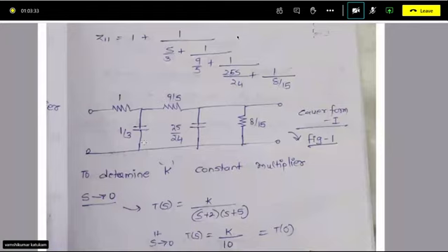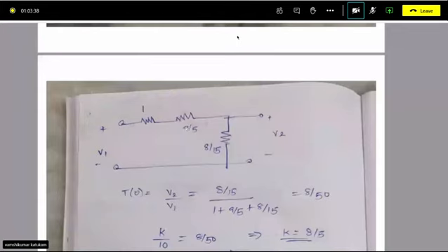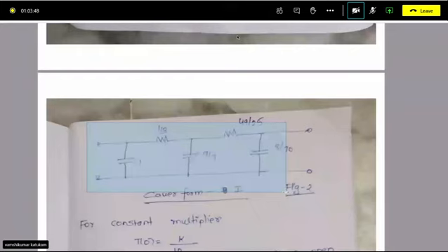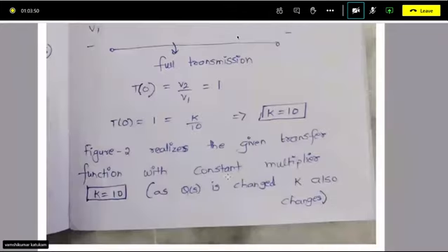Now, if you take capital Q of s with these 3 poles, 3 zeros, then you get this form, element values are changed, and K is equal to that. So for synthesis, depending on capital Q of s, you get a different network. In this same problem, if Q of s is changed, the final synthesized network changes, as well as the K value.